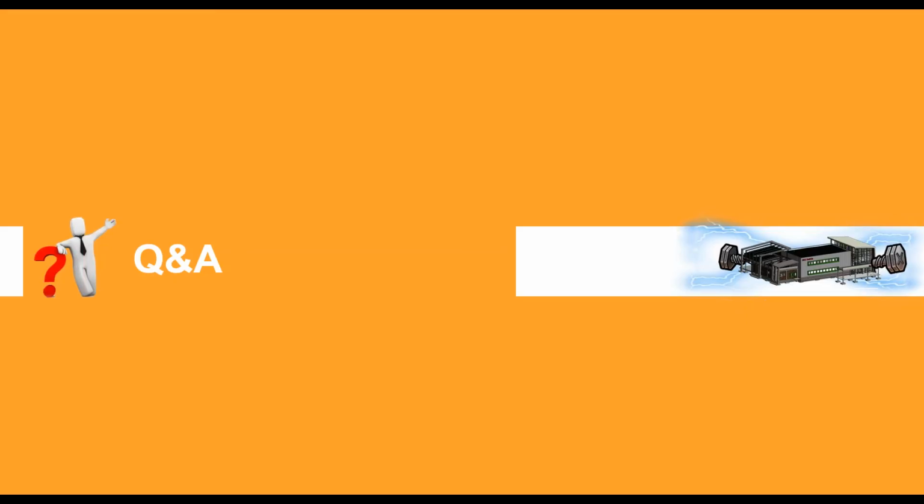But if you were in Stingray and you're like, you know what, I don't really care how it looks inside of Revit. I just want to make sure it looks really nice here. You can just make that change inside of Stingray. So if you want to tweak the translucency of glass, if you want to get a better image that you want to use for the wood grain, you can do that all inside of Stingray. And then from there, if you wanted to send it from Stingray into Live, then you can do that.